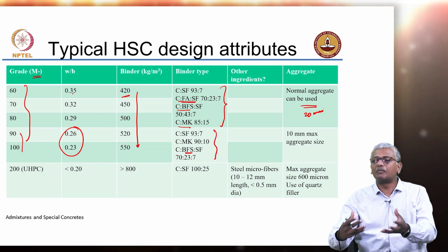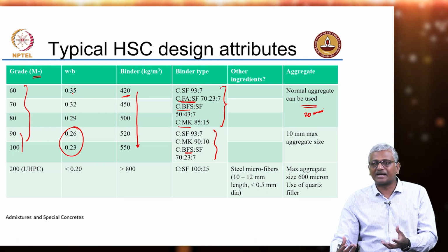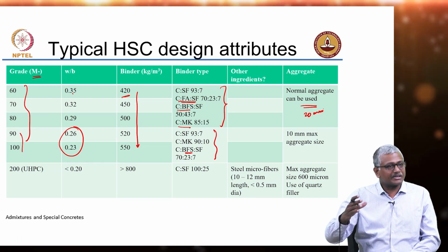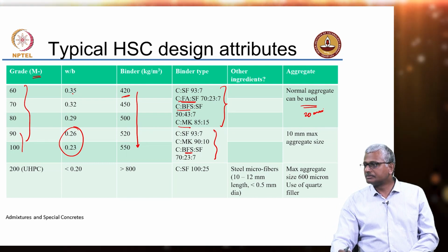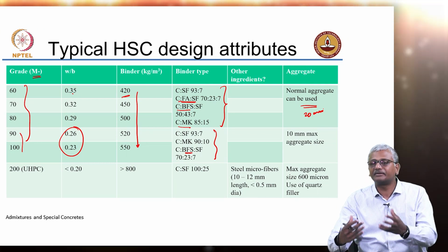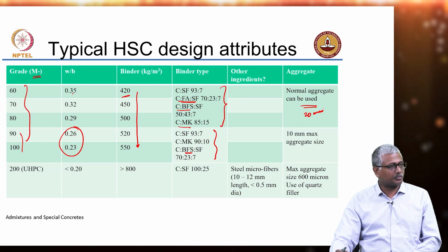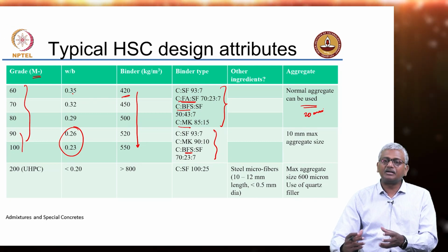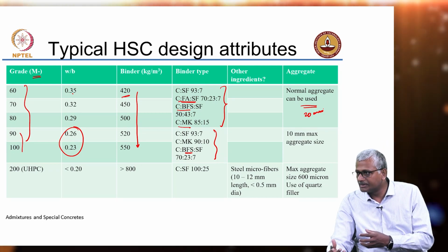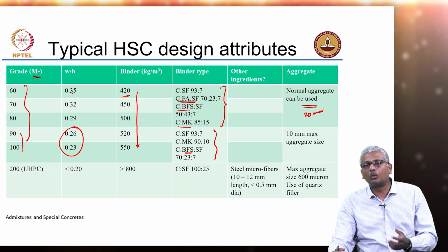So, when you are putting a greater number of small sized aggregates in the picture, the crack has to go through more aggregates, and that maximizes the strength that you can actually obtain, because the paste aggregate interface now becomes a strong component because of the low water to cement ratio.